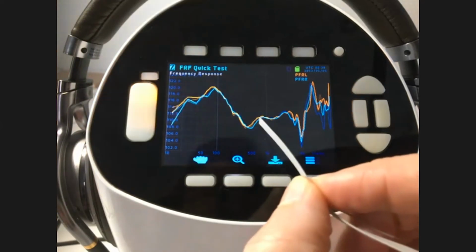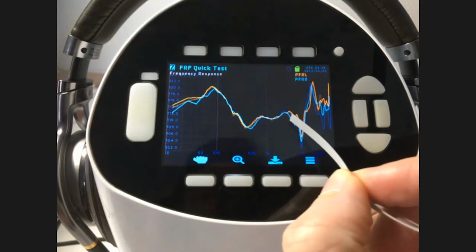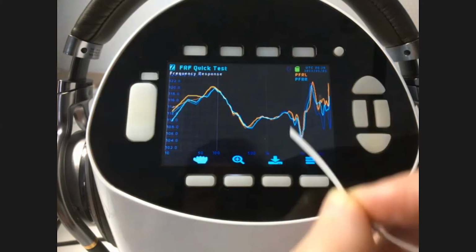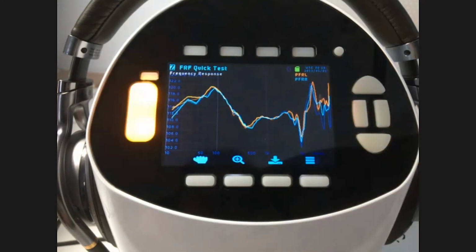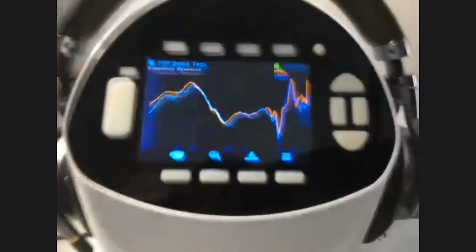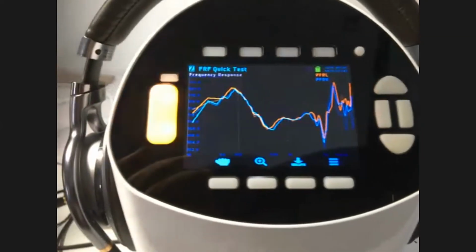Yeah. Okay, then we start off into this region where we go into the resonances, and it gets real busy in a big headphone because you have larger distances and a lot of different distances. So you might have sound reflecting from one side of the ear cup to the other, longitudinally and one vertically, and then from the ear plate to the side of your head. There's all manner of possible paths where you can get these reflections and standing waves set up.